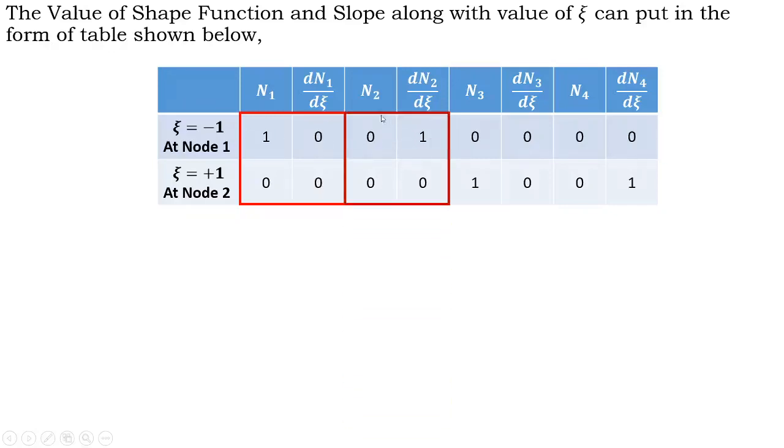So this is the second set of 4 boundary conditions to get the shape function for the slope. Similarly, for the third one, n3 is the shape function for vertical displacement at node number 2. Therefore at node number 2 under n3 I have a value of unity and the other 3 terms become 0.